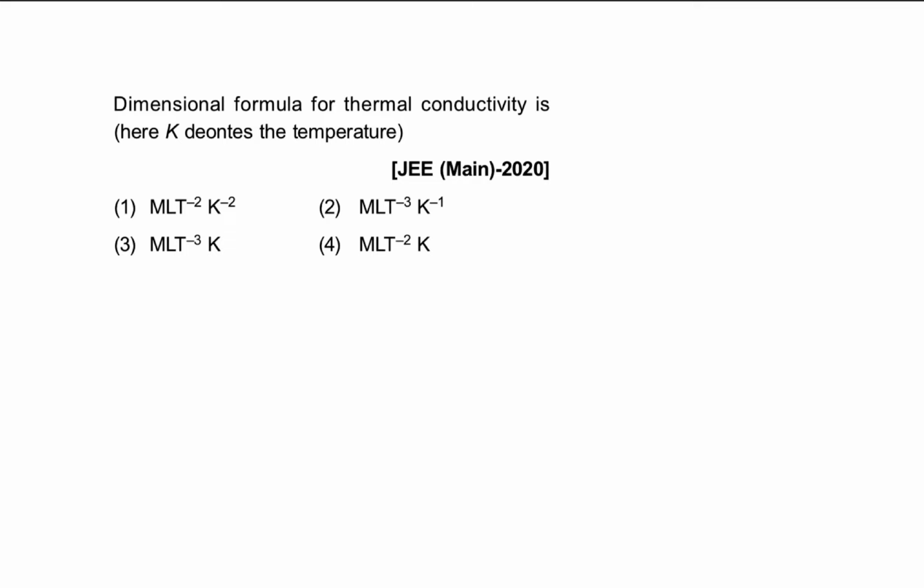Okay, so next question. You see a dimensional formula for thermal conductivity is, how to write the thermal? See, I have not remembered any dimensions except a few things like force, energy and all. Okay, you just observe this. Thermal conductivity. First of all, you should have the expression. What is thermal conductivity? You have studied Fourier's theory in heat transfer of conduction. We can write dQ divided by dt is equal to negative of K A into dT divided by dx.